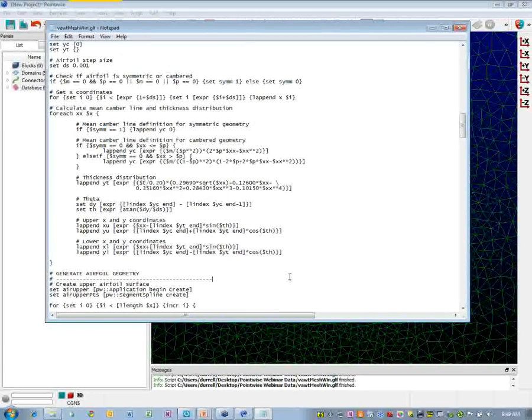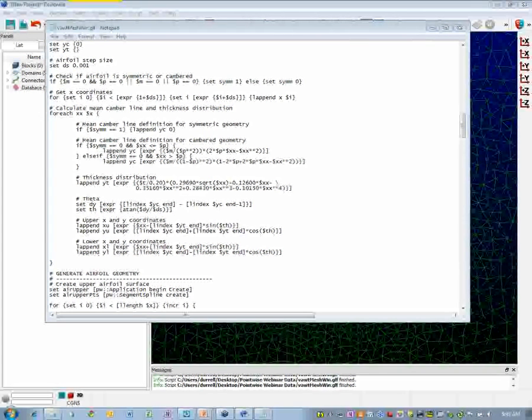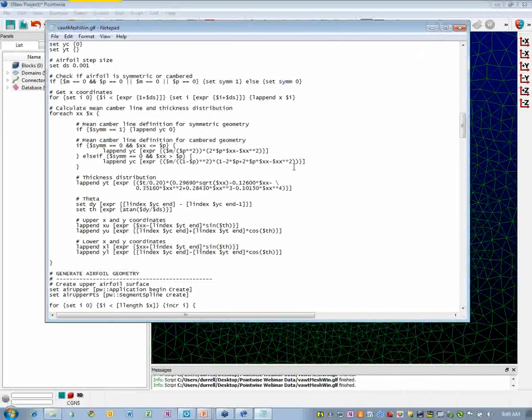Now it's dynamic, where you don't actually have to compile the code; it's interpreted, and so it's just storing all those variables that I either provide in the GUI, or in Travis's case where he ran it in batch. Those variables are populated with some sort of input, which in batch would have been driven by the output from the optimization algorithm, and so that's how it goes. Based on some sort of equation here, so I'm showing the equation for the airfoils, I can go ahead and generate the points that govern the shape of the airfoil, and then based on that, I can create my mesh.